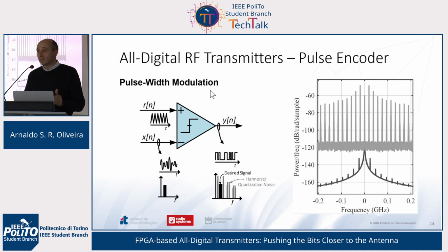In fact, the same PWM can be generated by a lookup table. If we have the lookup table, whose size depends on the PWM resolution, I can input a digital sample and the lookup table gives me immediately the representation of the signal in PWM. And this is, of course, a much easier way to implement in the digital world.